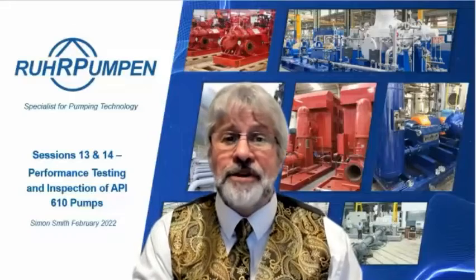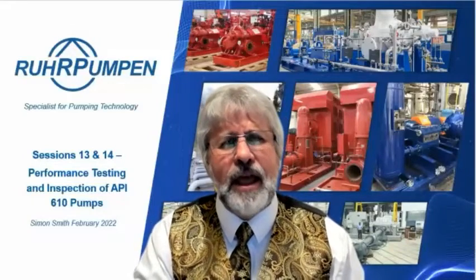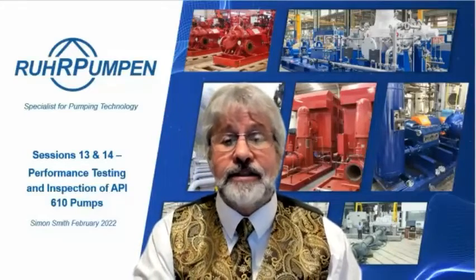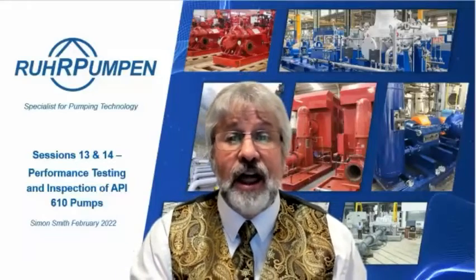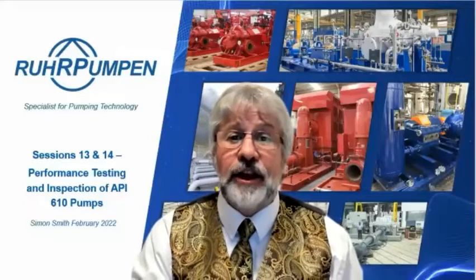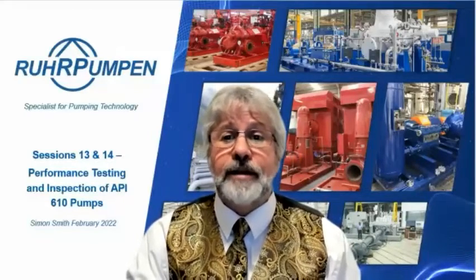A352, if I remember rightly, LCB, I think that's a low temperature steel, and so that would have an impact test. A216 WCB is normal steel. That's not suitable for low temperature applications, so it probably hasn't got an acceptance criterion for an impact test.